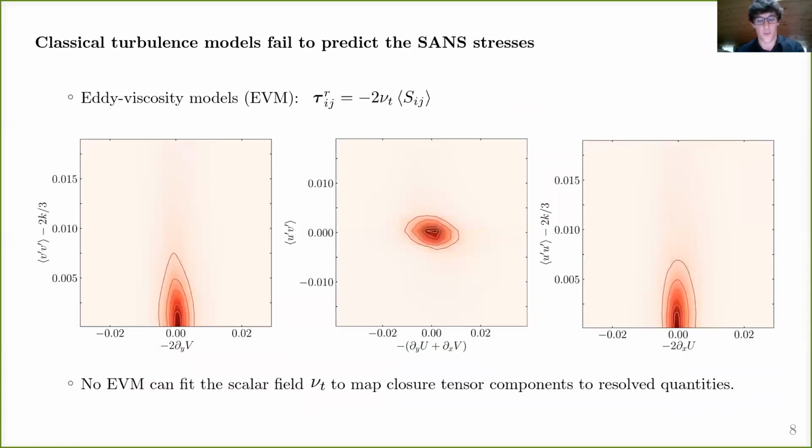So now we have a way to go from 3D to 2D, in which we account for 3D information that gives us back a physical answer on the forces induced on the cylinder. But we have some closure terms that we need to model. One might try to tackle this using some of the currently available closures for turbulence. But again, what we are trying to solve here are not subgrid scales or a dissipative term. What we are trying to solve here is a 3D-like term that, when you include it in your 2D equations, recovers the spanwise average solution.